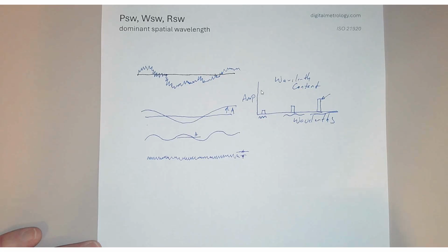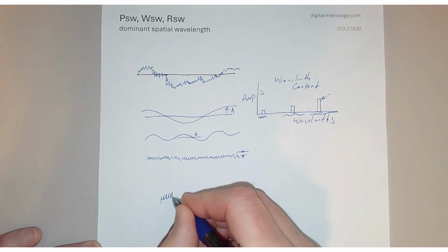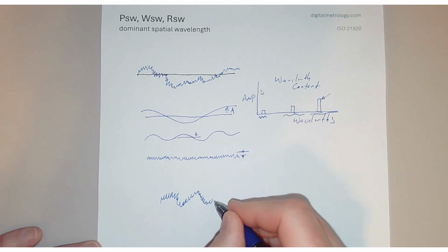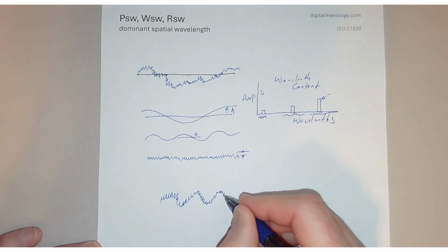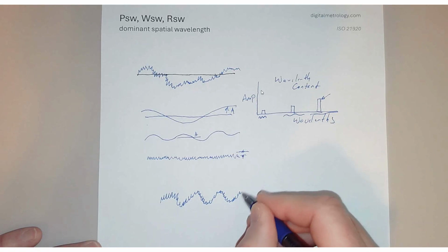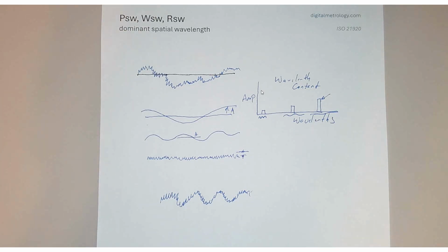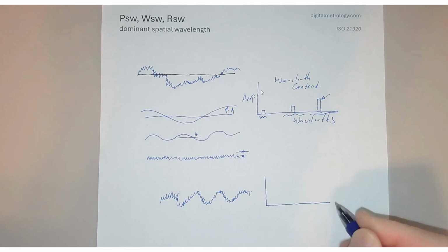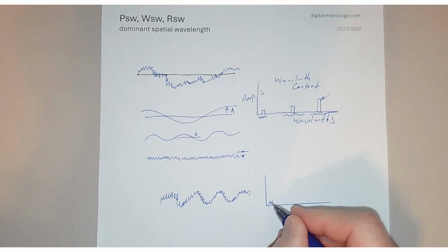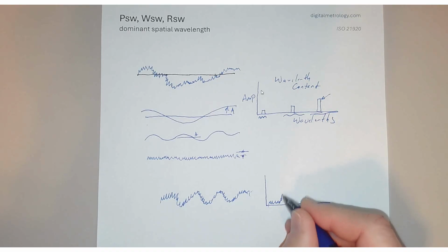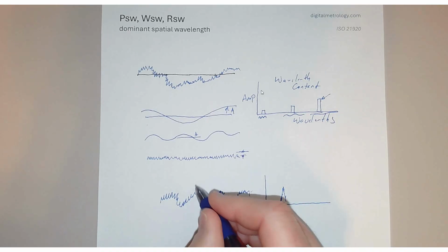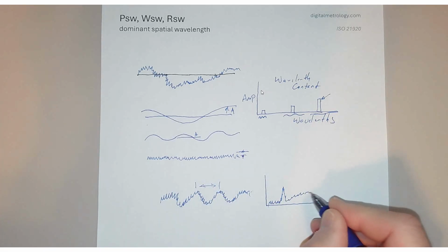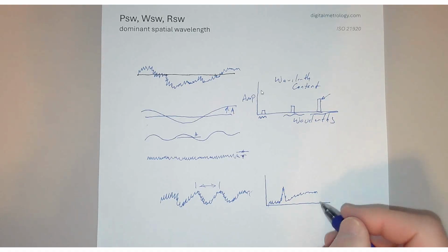Let's look at a different case though. Let's look at a surface that's kind of rough but has a strong wave in it. Perhaps in our machining process there was chatter. So this surface is a bit messy. It's not going to have pure wavelengths like perhaps the example I first drew. It will have this kind of wavelength content graph. It might have some roughness in it. It might have a very strong spike at one point due to this spacing right here, and then it may have some other things going on in it at the longer wavelengths.